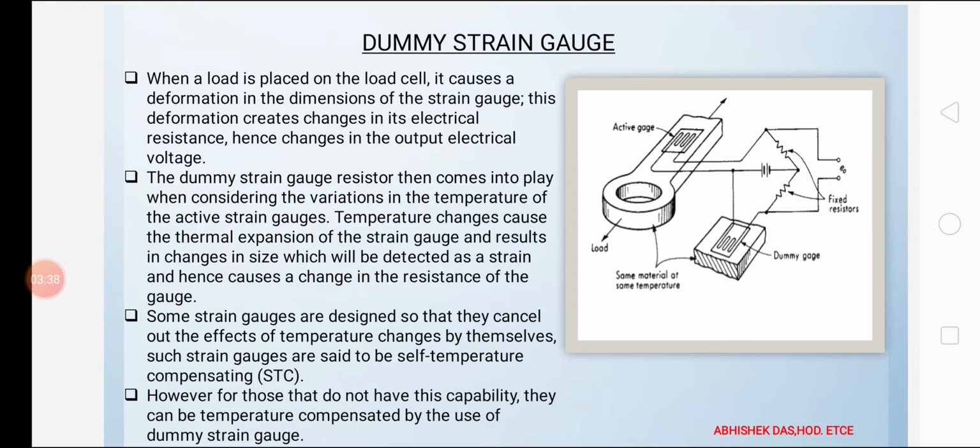The solution lies in having two identical gauges. One is a dummy gauge and the other is an active gauge. In the unity ratio Wheatstone bridge, the dummy gauge is connected to an identical surface, kept free from any stress, when both structures are under stress condition and at the same temperature the bridge is balanced. An equal rise in temperature of both structures raises equally the resistance value of both active and dummy gauge, and the bridge still remains balanced.